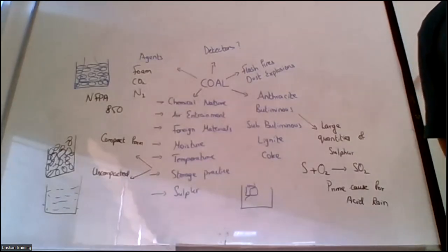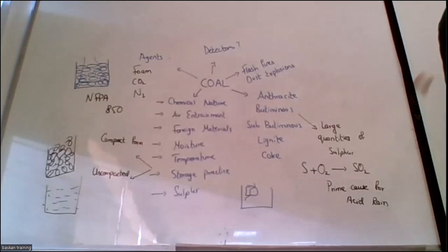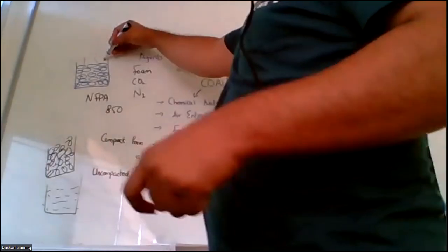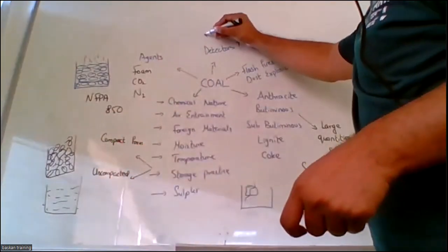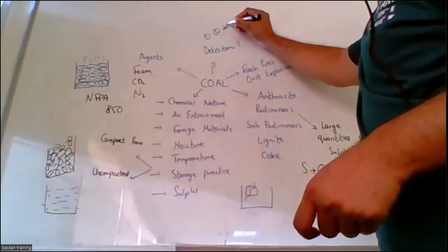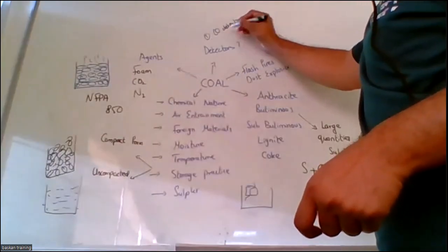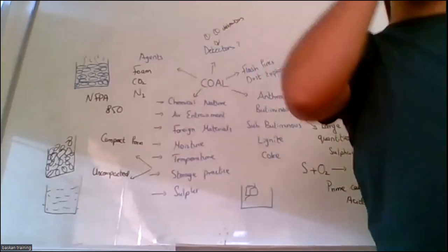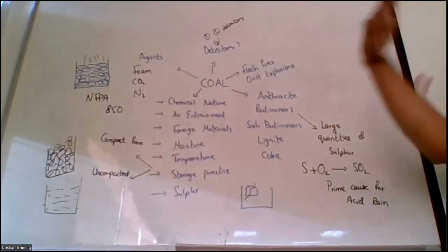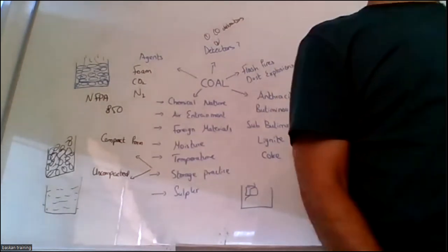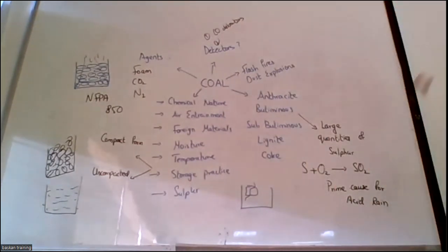Methane and CO are the types of detectors. Yes, we will use CO detectors, carbon monoxide, because we have discussed that carbon monoxide will be released. So one type of detector is the carbon monoxide detector. It is used to monitor the toxic carbon monoxide concentration. If it reaches above a set value, we want appropriate ventilation. Okay, what other detectors can we use?